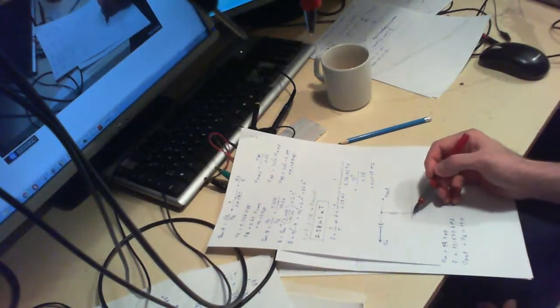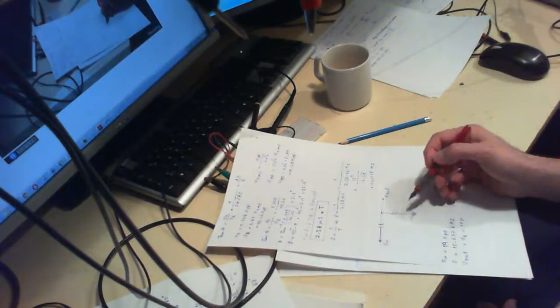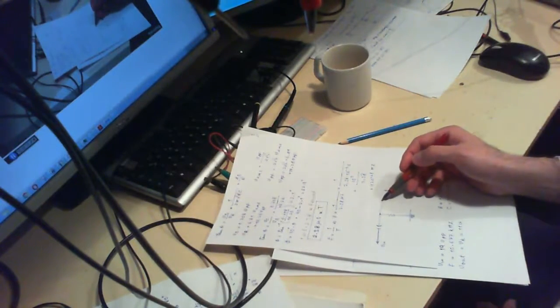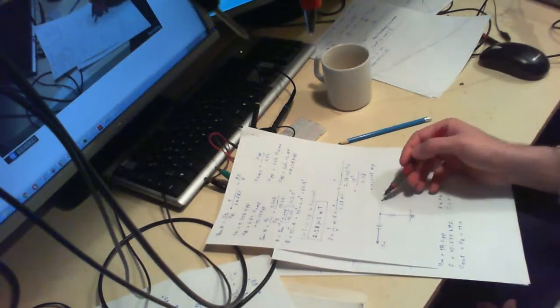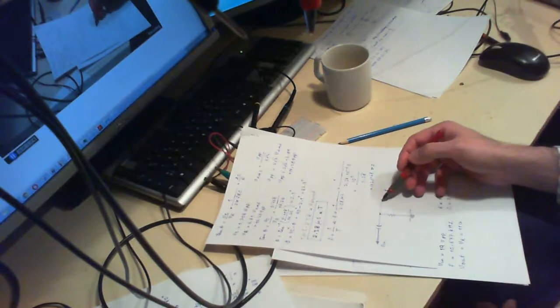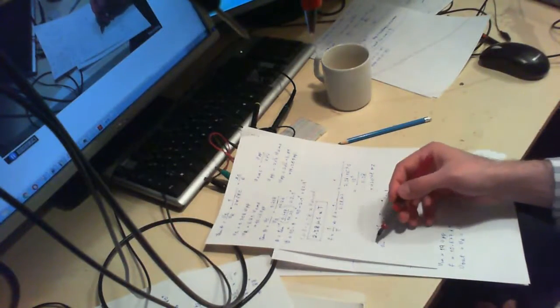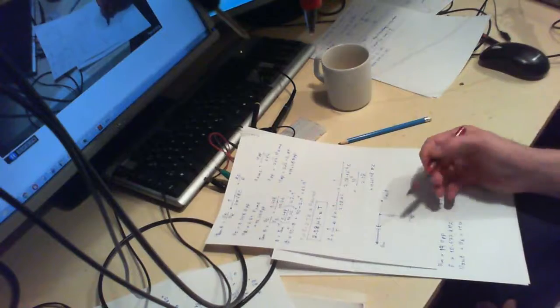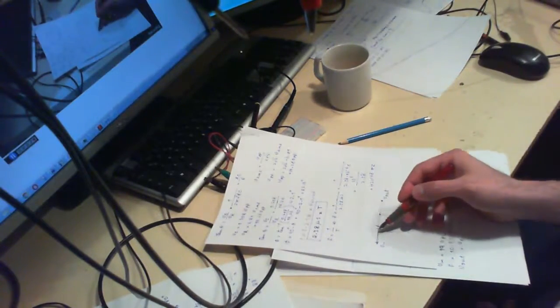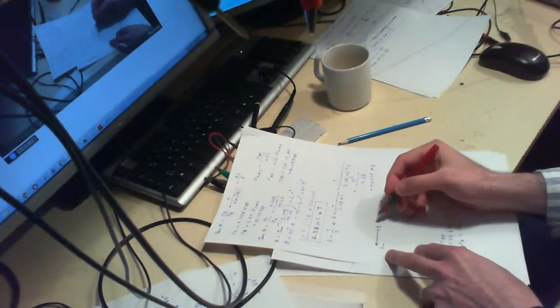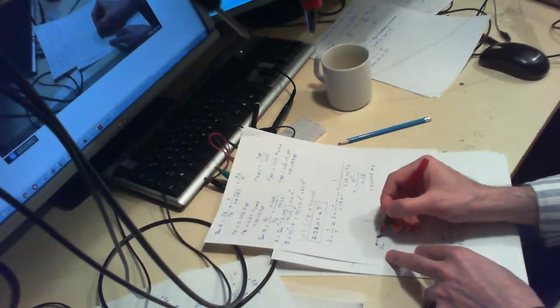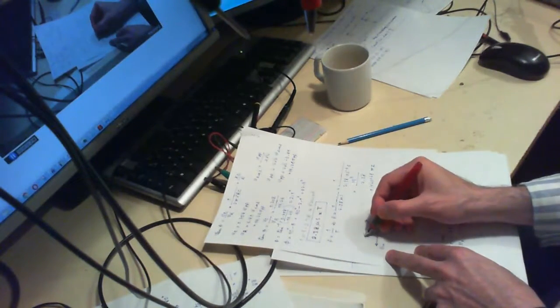For example, you could put your ground clip over here and measure the output voltage over here, the voltage across these 2 points, or you can measure the voltage across these 2 points, or across, for example, these 2 points. You can do that. But with an oscilloscope, you cannot go like a multimeter and take the voltage drop across these 2 points.